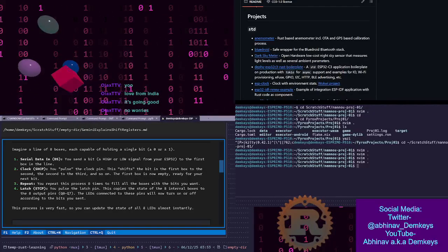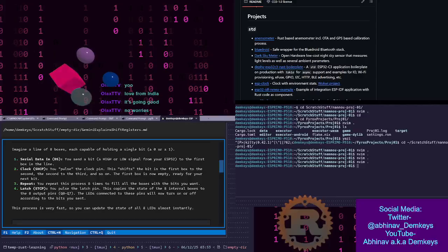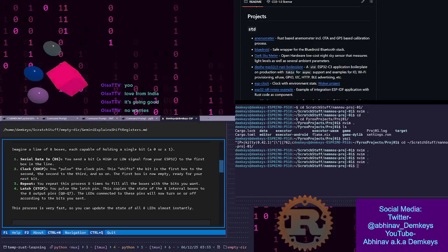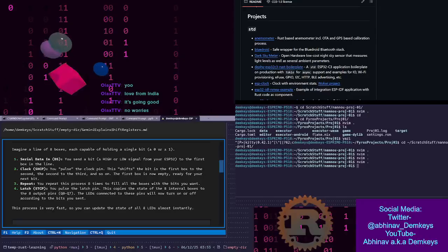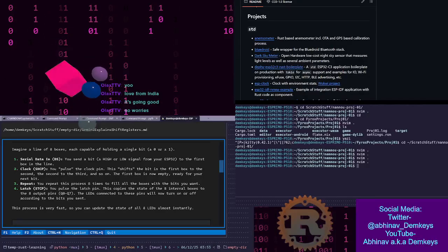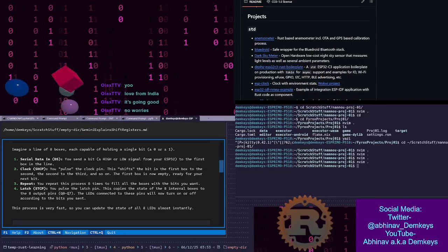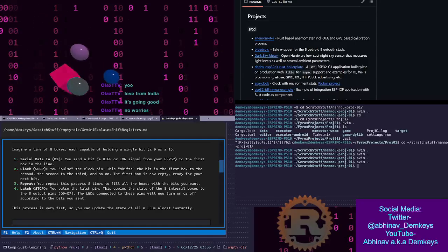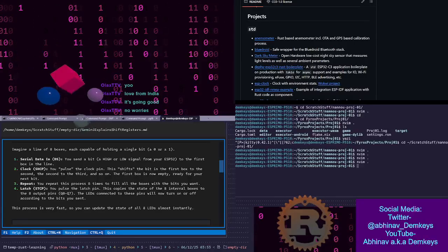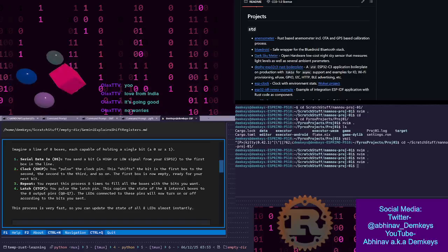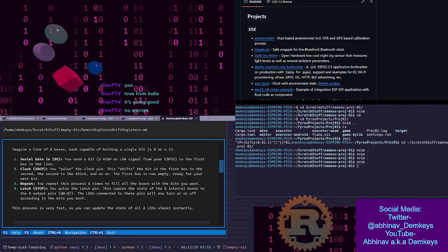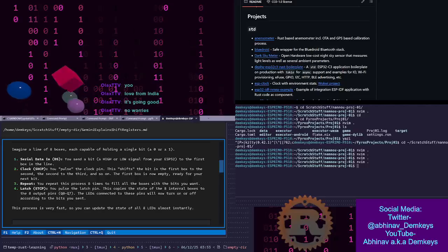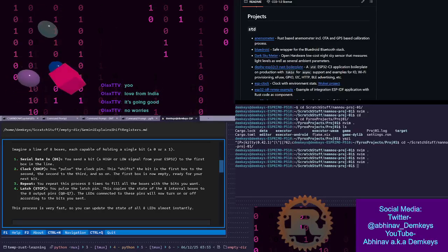You would be using some kind of communication protocol to send these 8 bits to the shift register through these, I don't know, 2 or 3 wires, right? You would be sending the data over to the shift register, and then the shift register would take those 8 bits and split it across these 8 pins. So that's the basic idea, right? Now let's see about the working.